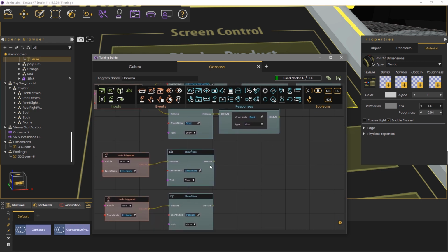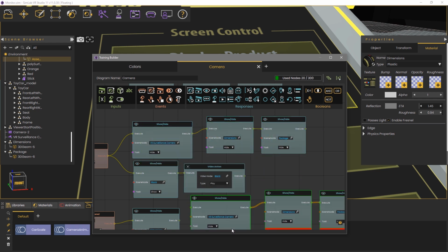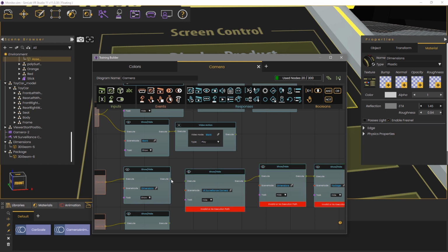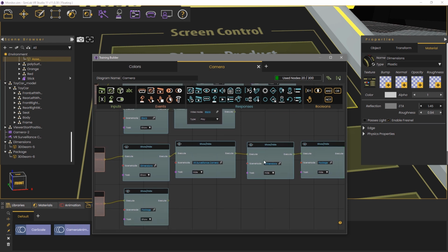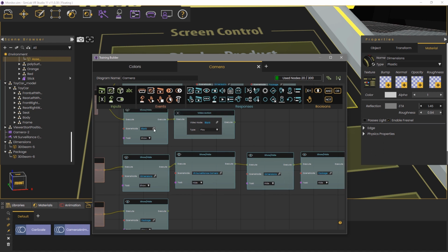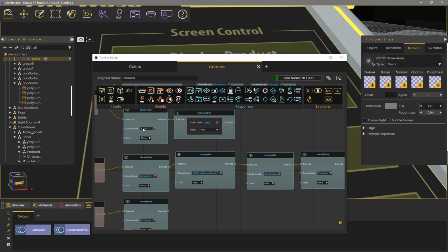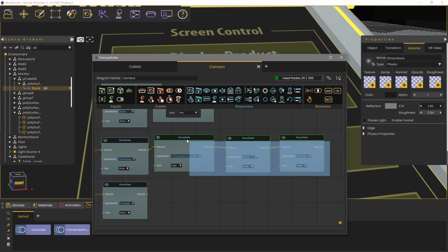As for the Dimensions button event, we needed to hide the package, the video, and the VR camera. So select the 3 hide responses from the previous event and duplicate them, then connect them to the Dimensions event system. As you can see, now we have a response that shows dimensions and a duplicate response that hides dimensions, which we should replace with the video. So click on the blank item from the above response to select the blank geometry which plays the video, and from the response node that hides the dimensions, click Attach to replace it.